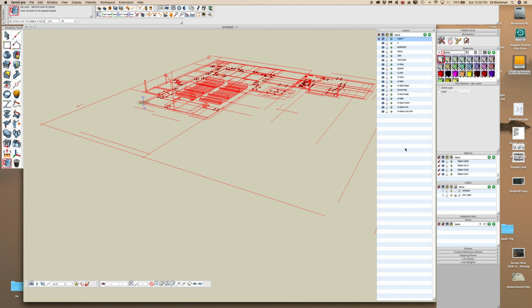Now just to double check, hold your control key down and click anywhere on that palette and go down and see where it says paste on active layer. You want to check that. Okay, now with the layer tool still selected over here, just click anywhere and you've moved everything that was in all of these palettes to this one layer palette.